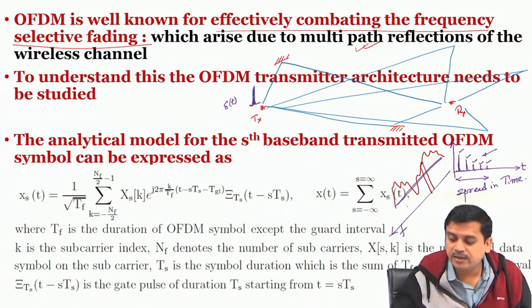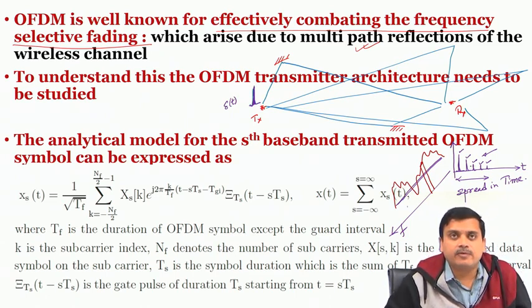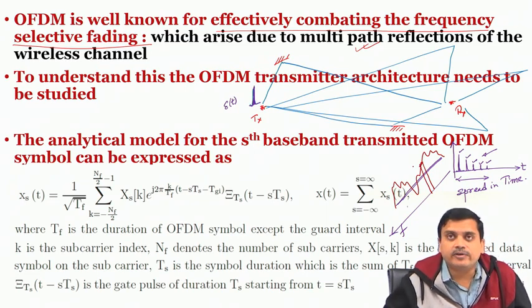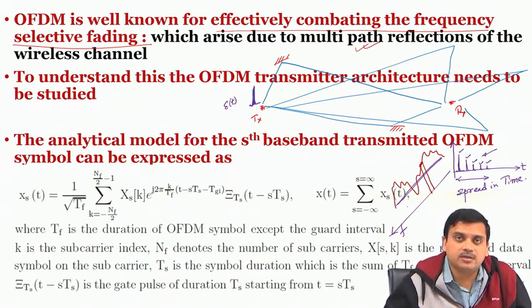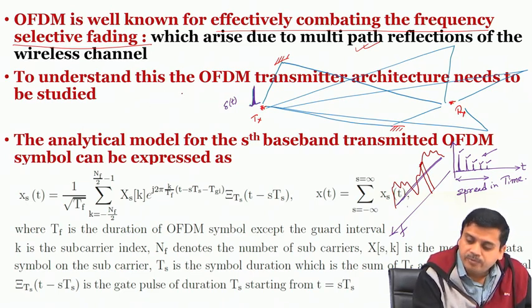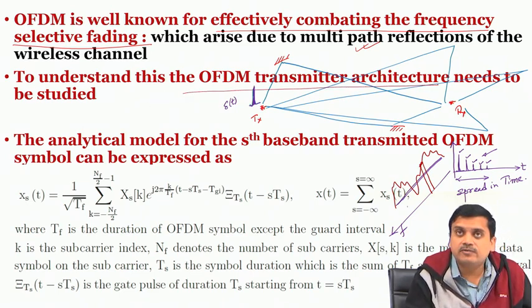So, one needs to understand the propagation characteristics very well in order to understand what the frequency selectivity and the multipath are, and how OFDM takes care of it. So, if it experiences a nearly flat frequency response, equalization is easier. That is again a huge advantage for wireless communications, because already you have a lot of extra complexities. This is only going to help reduce the complexity that is to be addressed. Okay. So, this way we will proceed towards studying the architecture of the transmitter.